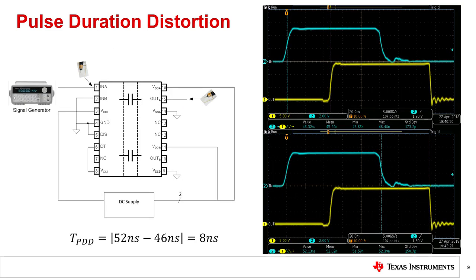To measure pulse duration distortion, the same test setup as propagation delay is reproduced, and data is collected for many pulses across duty cycle until pulse durations become comparable to D-glitch filter cutoffs. For drivers with programmable dead time, the feature must be bypassed. Statistical collection and persisting capture data are both helpful ways to observe the pulse duration distortion.